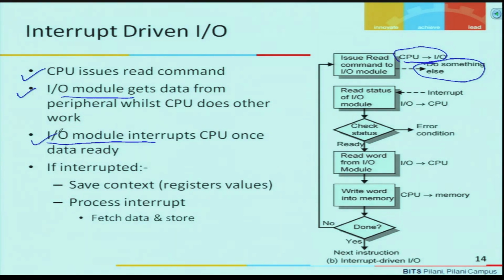So here the difference is that the device or the module is sending a signal to the processor indicating I am ready with the data. In programmed I/O, the device is not sending anything, everything has to be done by the processor. The processor has to continuously monitor that status register, and the device from its own side sends nothing. That is the difference.